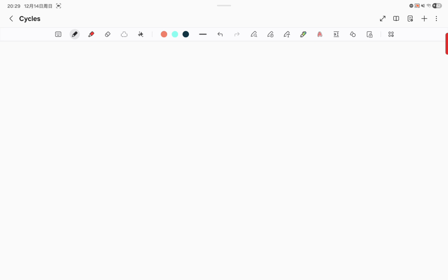Instead of having a pump, we have compressor because air can be compressed, and we do not pump air, we pump liquid water. So in this case, this is Brayton, since it is ideal gas. So the first component I'm going to draw is compressor. Same thing, there's no boiler here because we do not boil water. Well, we do not boil air, we burn air. So that's called combustion chamber.